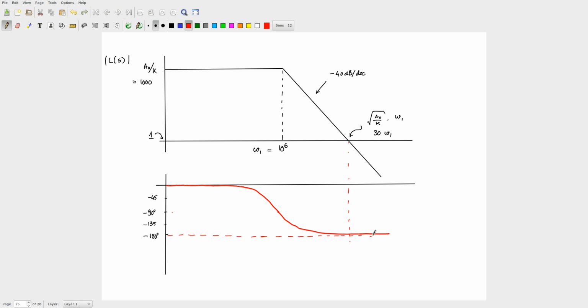okay, good. With the compensation, how will it look? This is 10 power 6, and what is my compensated value of omega 1? Just by putting that C alpha, I am not doing Miller compensation yet, just with C alpha. What happened to my P2? P2 remains here, right? This is omega 2 equal to omega 1, right? Both are identical for the case without the C alpha.